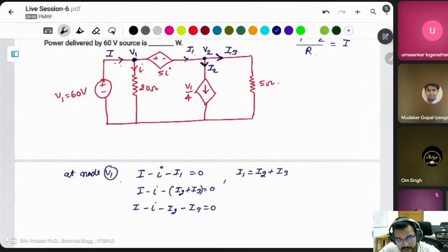It means you can write the same equation as a single equation for the two nodes because of this. Because you can't find the current in this branch, this branch current is divided into two parts, then you can directly write these two currents. Then KCL will be satisfied at node 1, like V1. This is the concept of super node.